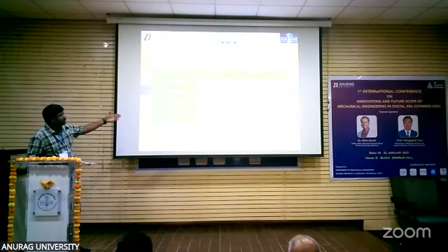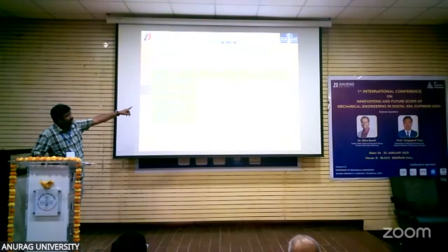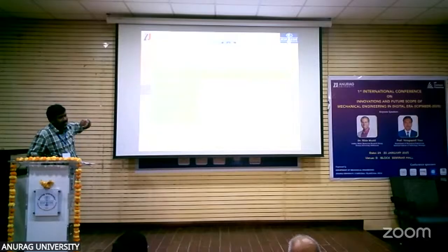Now, these are the results I have got. We got the stiffness factor and the toughness in the Izod impact test. NW means new wood, which we did not test; we directly took it. After testing at 5 hours, 17 hours and 24 hours, we have taken 3 woods, and we got the values 0.02, 0.04 and 0.05. For the Brinell hardness test, I got 13.69, 14.99, 22.57 and 23.57. That is the Brinell hardness number.